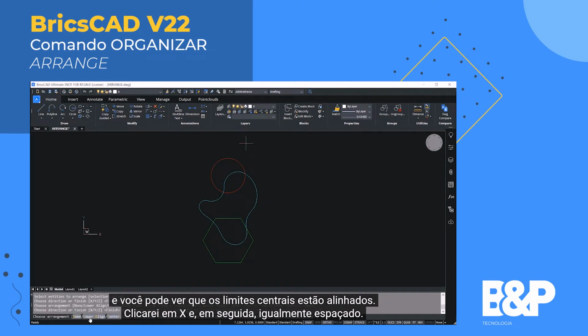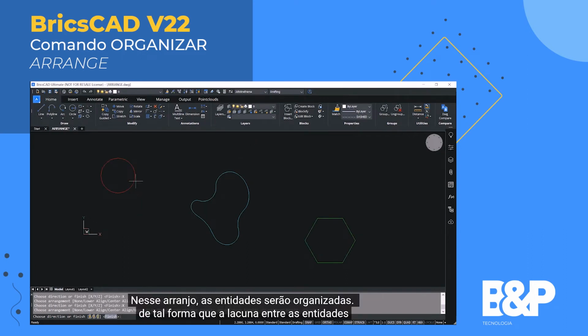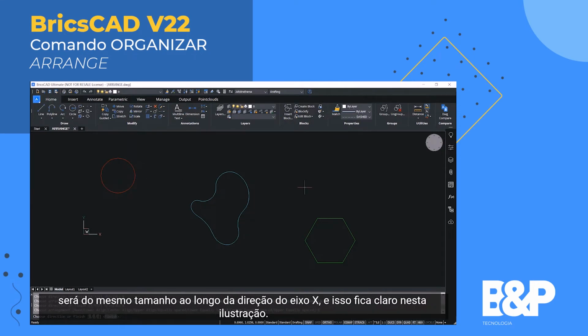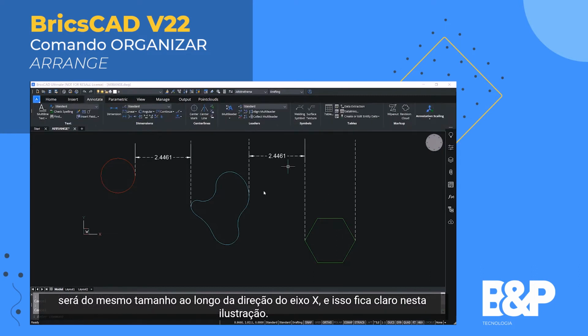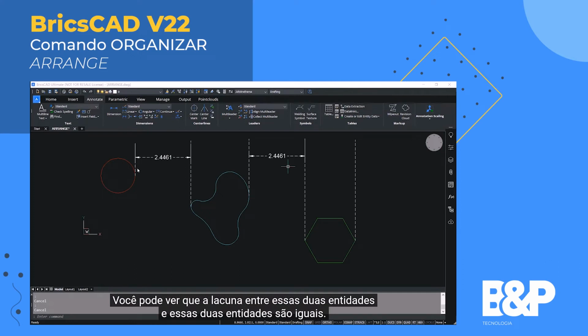I'll click on X, then equally spaced. In this arrangement, the entities will get arranged in such a way that the gap between the entities will be of the same size along the x-axis direction. And that is clear from this illustration. You can see that the gap between these two entities and these two entities are the same.